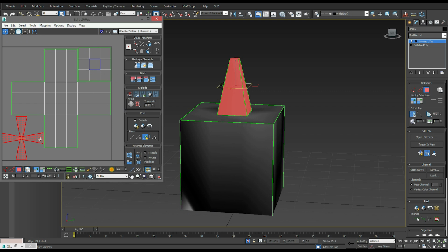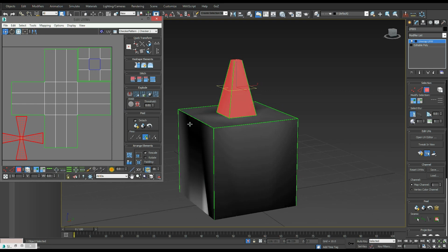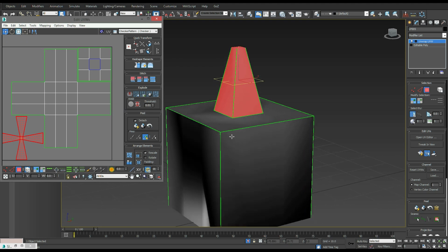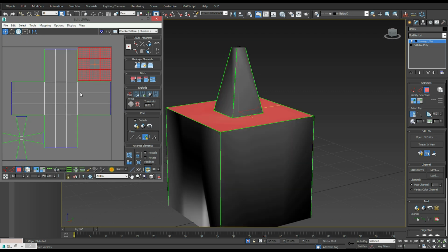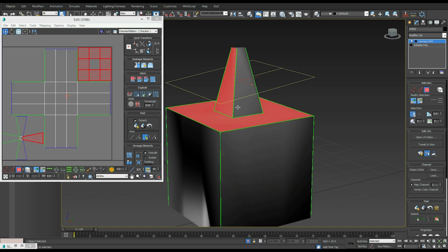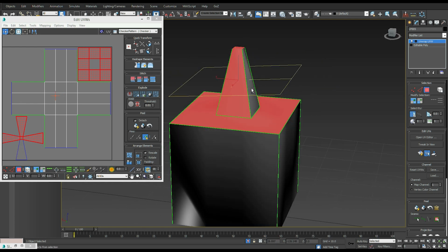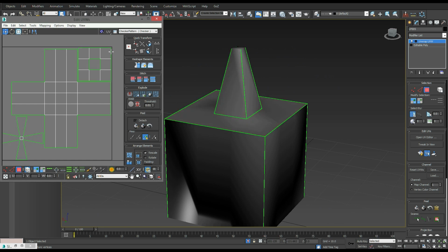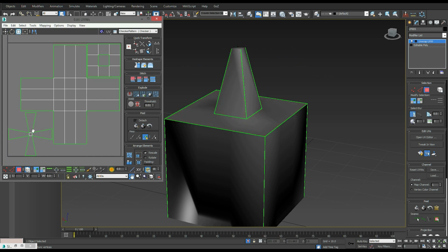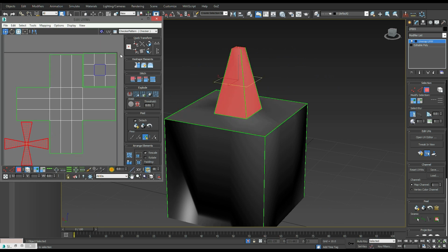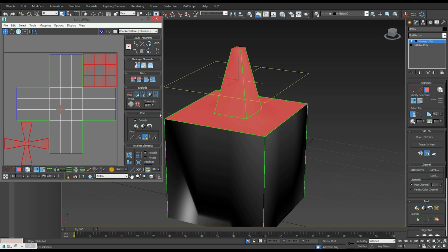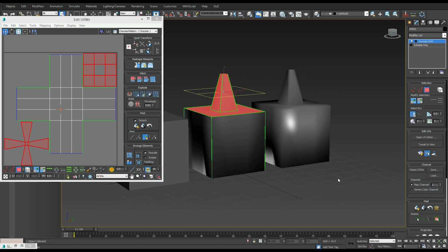That doesn't really matter. So to recap, if you have a separation in smoothing groups, you have to have a separation in your UV islands. But if they're together, like these are here, you don't have to. You can have it either way. So I could have, for example, split this all apart and welded it all down onto here. That would be perfectly fine, having those two together. But that's what I wanted to go over on this one.